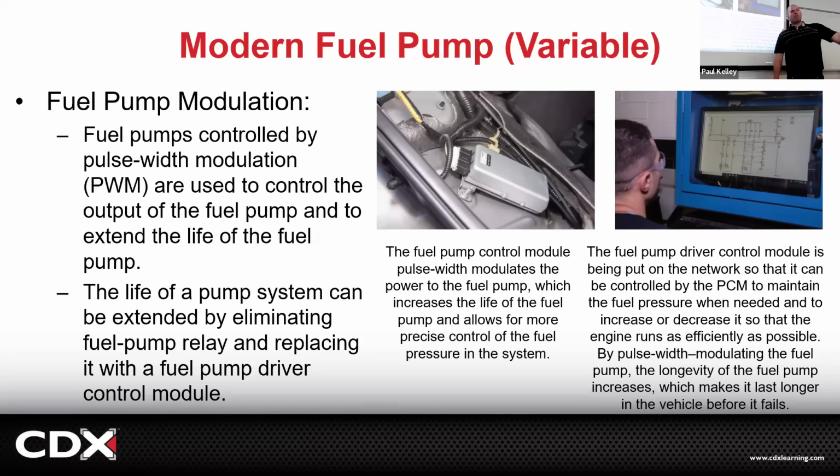What is giving the on and off signal though? Modules. Yeah, a lot of times it's going to have a fuel pump control module. Sometimes the PCM or the ECM could do it, but a lot of times we'll have a fuel pump control module, and the ECM or PCM will send out a command to it. Hey, we want this much fuel pressure. And the fuel pump control module will be like, oh, okay, that's like a 50% duty cycle. Do half on, half off. Oh, you want more? 60% on, 40% off, right? So the fuel pump control module now does that.